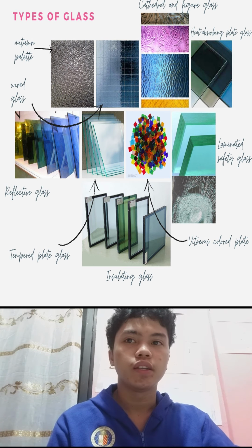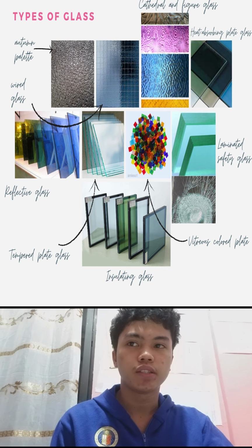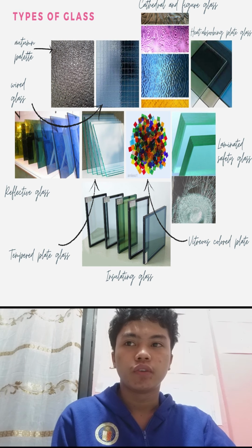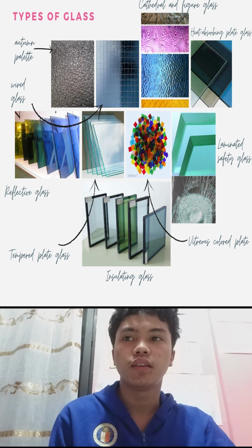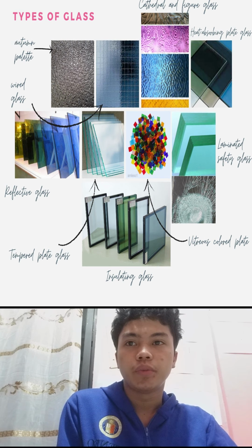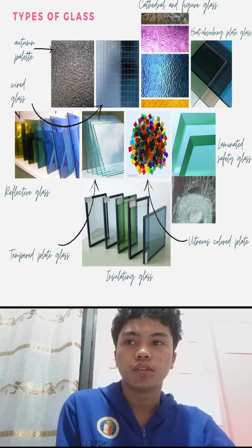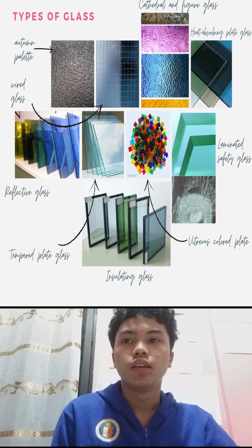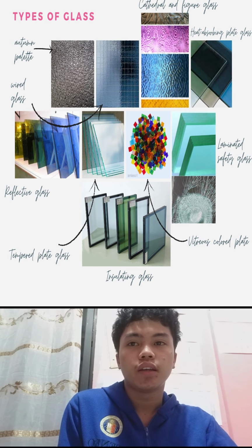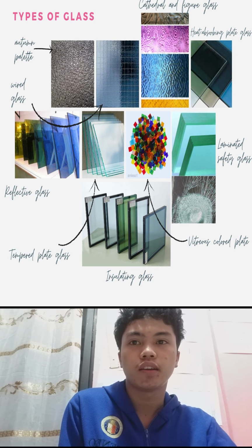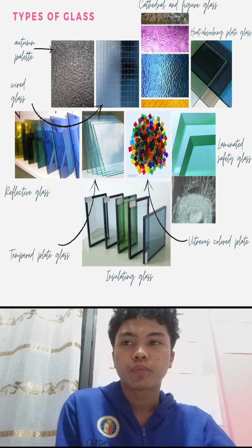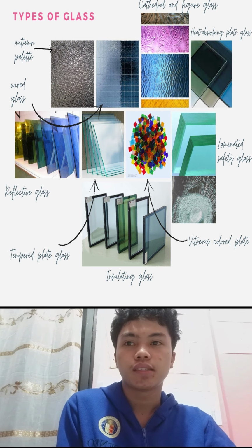A chrome coating provides silvery outdoor reflections and creates a cool effect during the daytime, while being neutrally transparent from the inside. At night, the glass reverses itself by being transparent from the outside and semi-reflective from the inside. Reflective glass is commonly used for big projects such as high-rise buildings or even medium-rise buildings. In several architectural designs, they are used as green sustainable elements for their high performance against heat ingress and delectable visual effect.